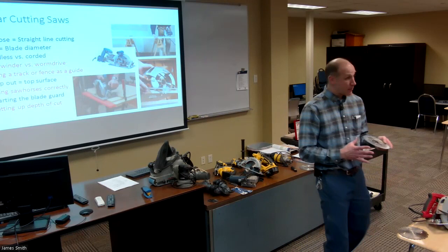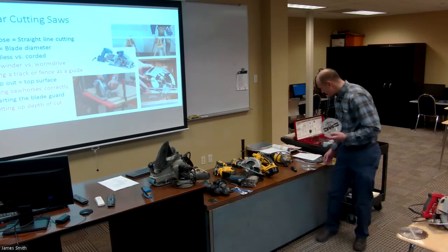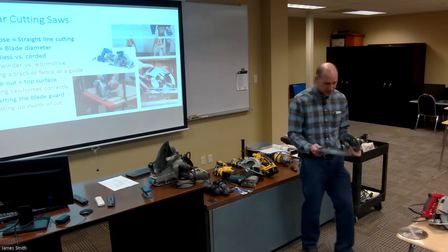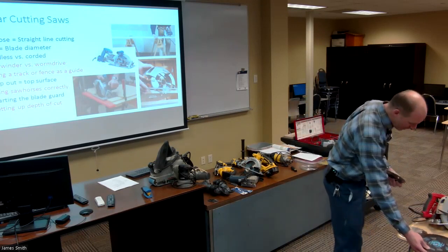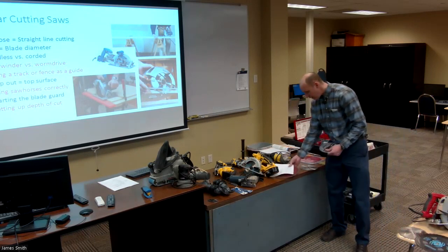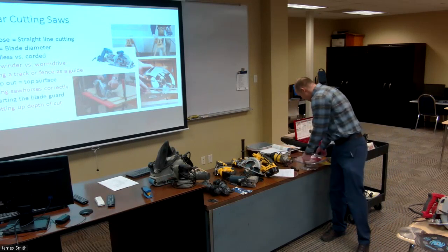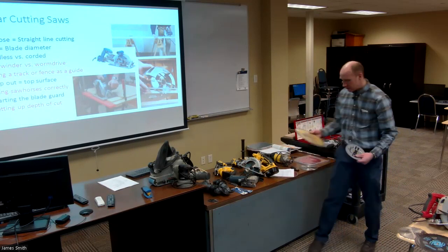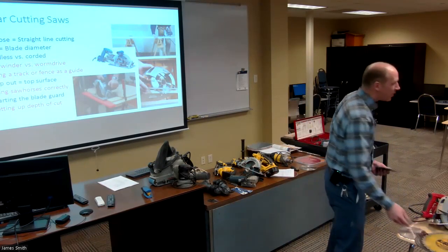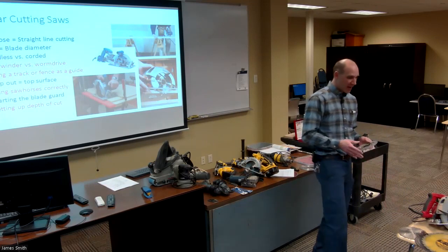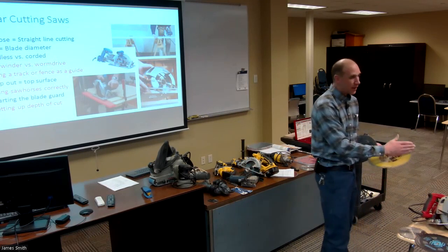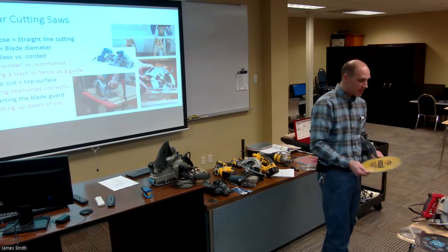You can also buy different diameters. So there are different types of saws. Don't get those confused with a table saw blade, which you can buy in a 10-inch diameter. And then the miter saws are generally 12. You can buy miter saws that have different diameter saw blades. Here's a 12-inch saw blade. Generally, the ones that they sell for the miter saws will have a different rake angle, because they're generally used for cross cutting, and a flatter rake angle performs a little bit better.